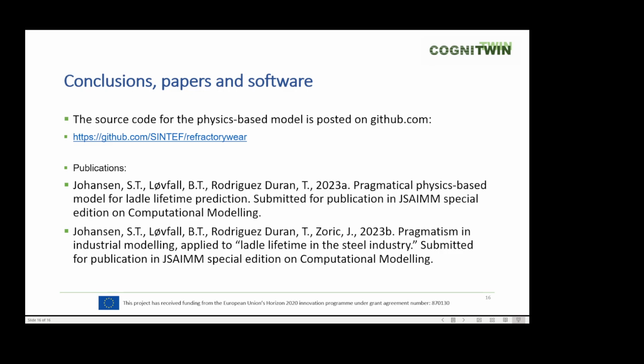In this case, the model can be used in a semi-quantitative manner. Therefore, the combination of model predictions, visual inspections of ladle refractory and operators' experience altogether make the foundation for the operator's decision whether the lining should be demolished or not.